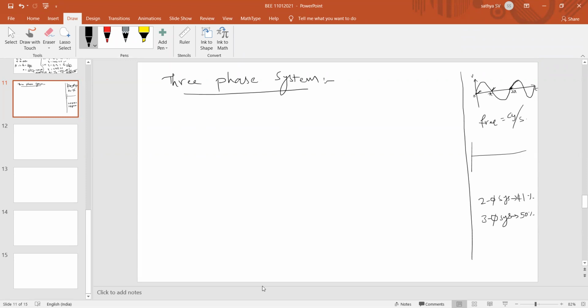That is from single-phase to three-phase system. Now they crossed the three-phase system. Beyond the three-phase system, the maximum possible increase is only 7%, however many phases they add. But even for this 7%, if you wish to continue, there will be more complications in the circuit. Understand? So that's the reason we stop at the three-phase system.